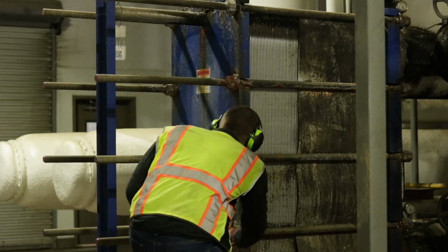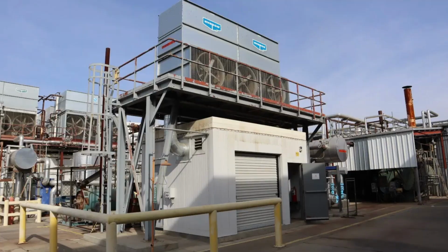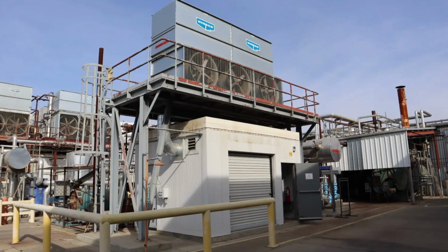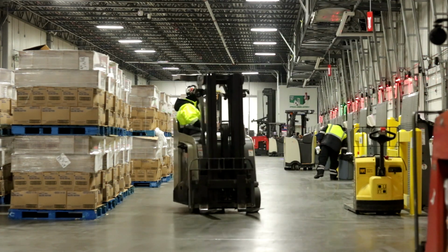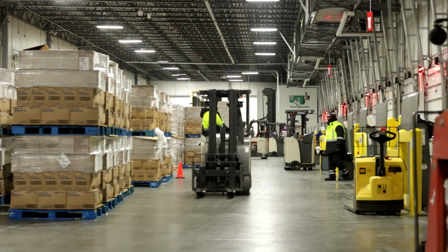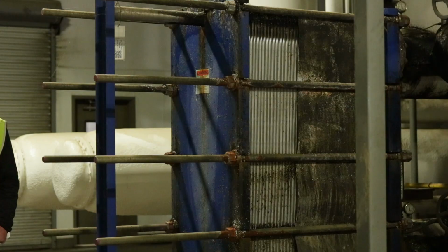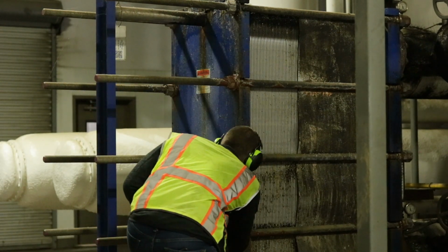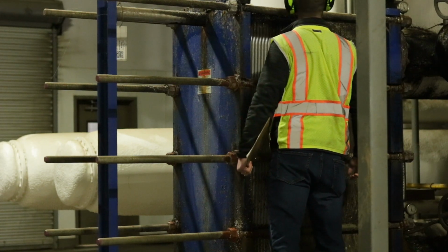Instead of piping refrigerant throughout the plant, the secondary coolant provides the cooling, and the refrigeration system is limited to a central machinery room or area. This is particularly attractive when ammonia is the refrigerant because it limits the area where personnel might be exposed if a leak occurs. However, it is important to emphasize that any time a secondary coolant is used, the refrigeration system will be less efficient than when employing direct cooling.